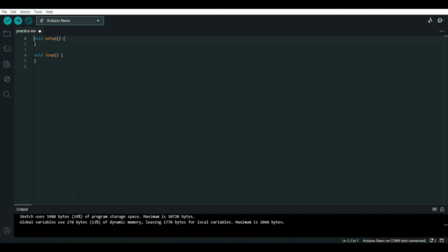Open up the Arduino IDE, and the first thing that you are going to do is to include the LiquidCrystal library. Then you can make the trigger and echo variables for the ultrasonic. You can also check out the previous videos in this series if you want to get familiar with the functionality of the ultrasonic sensor. Now we will configure the LCD pins. And after that, we need to make an object of our LiquidCrystal to be able to use it later.